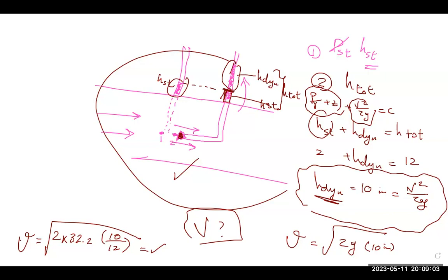Right, both are entering the pipe. Yes, but the first pipe does not affect the flow and does not make stagnation. The second pipe makes stagnation. Then the liquid will rise in both of them, right? Yes, but the first one just reflects the static pressure. But for the liquid to rise, it will have some velocity, then it will rise.